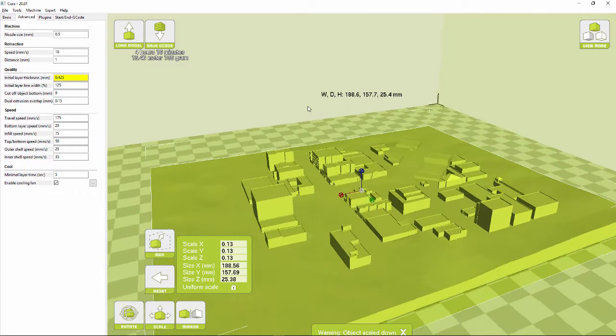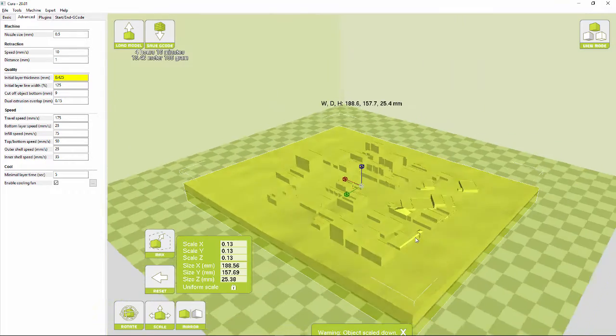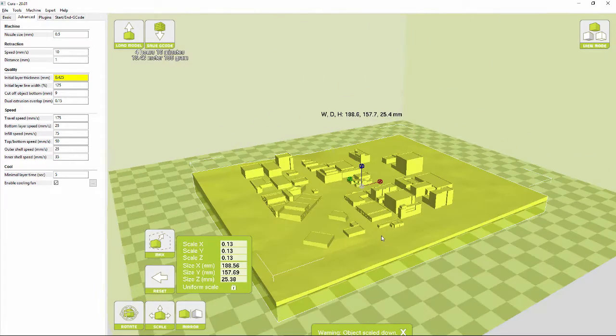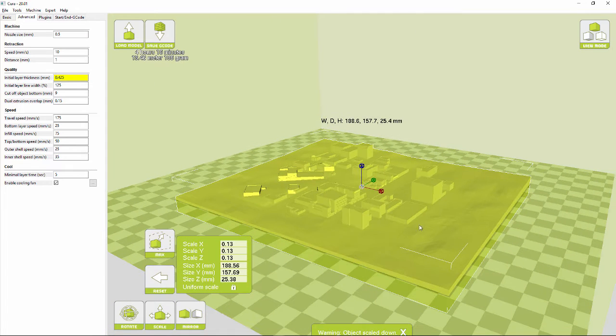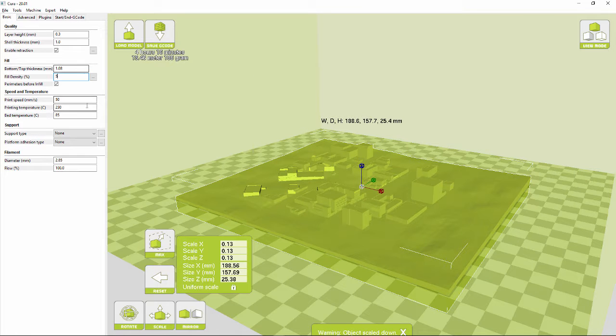The other things that I would note, and again, I'm not going to film the entire printing process. Just want to run through this so you can understand the settings, how to import and how to use the scale factor. The other things that we can take a look at that can significantly improve speed are going to be the fill density. For most architectural things, we use about 5%. And the basic print settings.